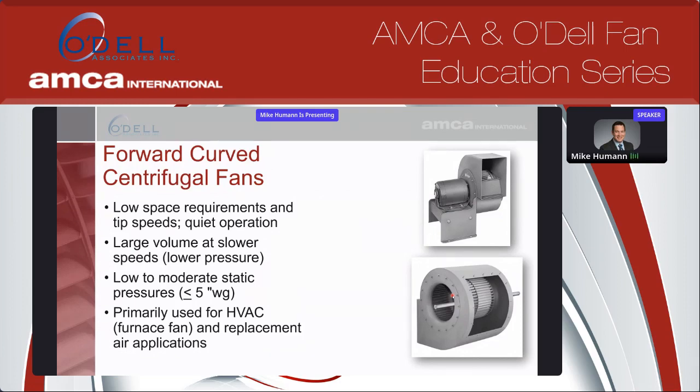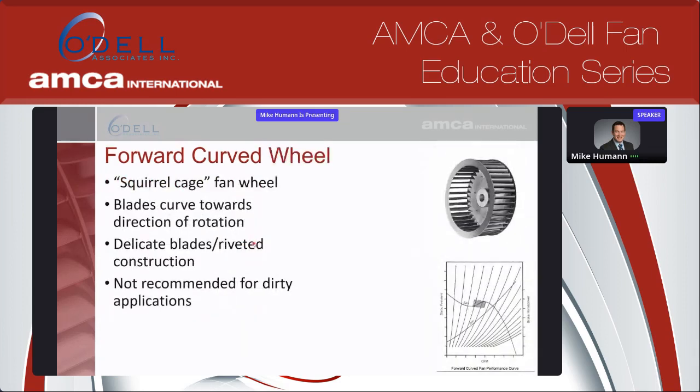You also see forward curve fans, and with the forward curve fan, you'll see that you have a wheel here that has many blades, cups air, and relatively for the size, they move high volumes at a very low static pressure. You see these in a lot of HVAC furnaces, replacement air applications, and they do tend to run at slower speeds. They're just not inherently designed to run high speeds. It's also called a squirrel cage in a lot of applications or different industries.